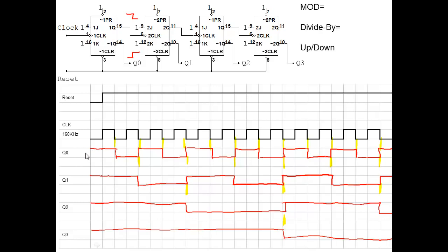All right. Again, least significant, most. This one's going to be 1 1 1 1, 1 1 1 0, 1 1 0 1, 1 1 0 0. And what is that? That's 15, 14, 13, and 12. Because remember, you've got 1, 2, 4, 8. Add those up and it gives you those numbers. So it sure looks like we're a down counter.